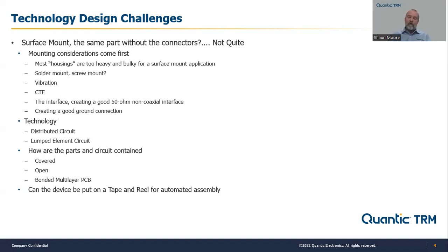The housing for most RF components does play a bigger role in the component design than just supplying a carrier. And I think that is a mental leap that needs to happen, is that most housings are indeed part of the RF circuit, and by eliminating the housings, you are therefore modifying the way that the circuit is being designed.